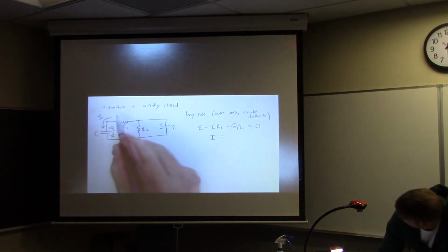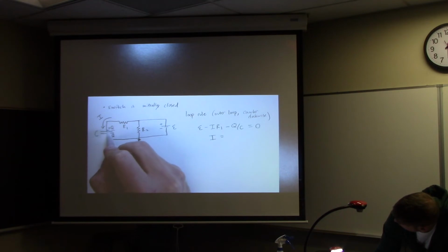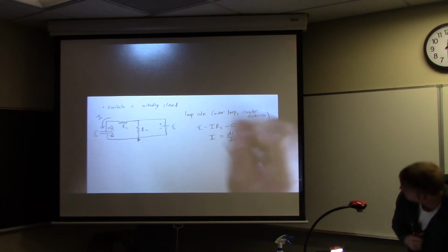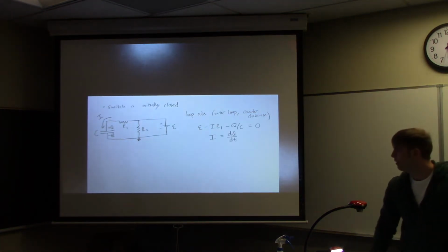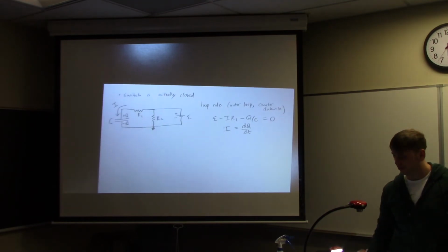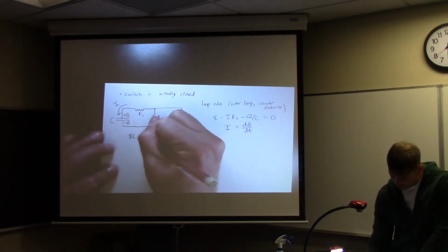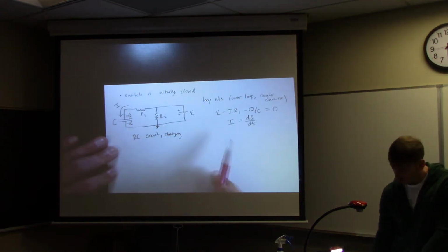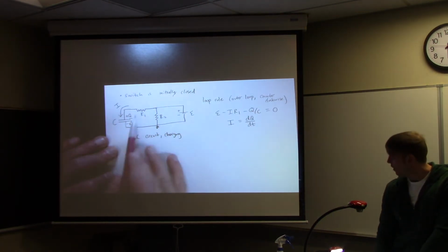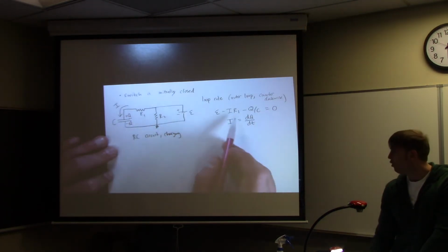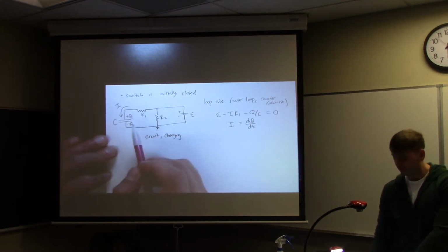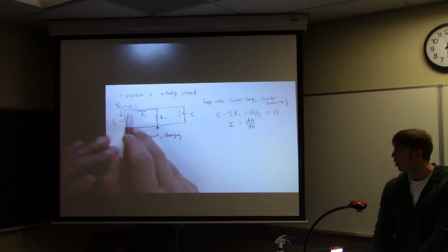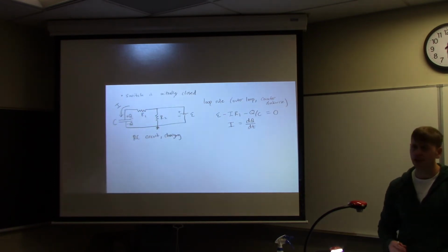How does the current here relate to the charge on the plates? Well, this current is really just giving me the time rate of change of the charge on these plates. It's just dQ/dt. So, okay, at this point, we don't need to go much further. This is an RC circuit charging, where we just use the C value here, but we use R1. Because what's happening? The capacitor is charging through resistor number 1. R2 doesn't actually come into play here.